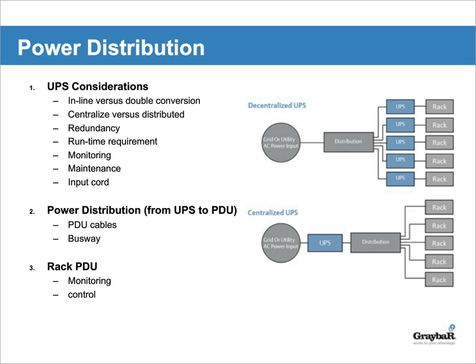I think I can say that if you have the option of going with a central UPS, you should, right? It is more economical. It is easier to maintain. It's much easier to maintain one piece of equipment than to maintain multiple pieces of equipment, right? But it does imply that there will be a lot of work in the building, right, to bring the power from that central location to the rooms. So a lot of times that's not feasible, right? But I think rule of thumb, if you can go with a central UPS, you should, right?